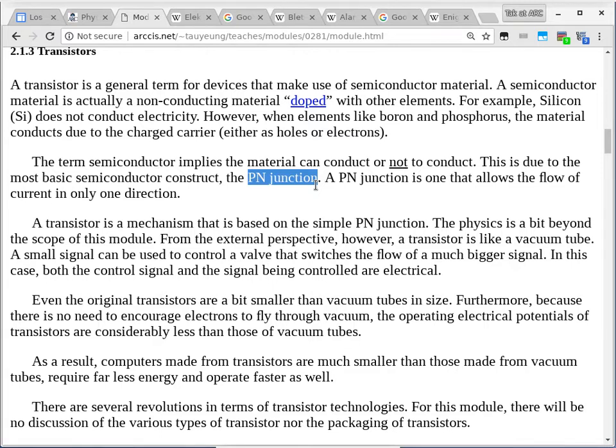So if we use silicon to implement computers and we say those things are transistors, they have to conduct current. So how do we make something that does not conduct current into something that does conduct current? We dope it. That's the actual technical term. We dope the silicon material into something that is conductive. How many people here have taken basic chemistry, like college level chemistry? Okay, so if you look at silicon, how many electrons are on the outermost orbit?